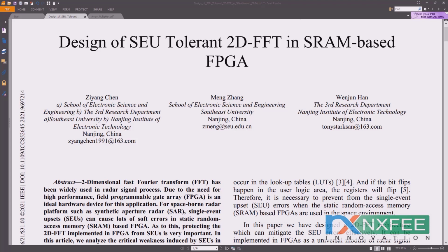This design takes advantage of many anti-SEU techniques. Triple modular redundancy (TMR) is utilized in the FFT butterfly control, and the data buffers are read and written with error correcting codes. Furthermore, the critical storage registers use secure finite state machines, and the findings of fault injections revealed that the reinforcement approaches help to improve the capacity to attenuate SEU impacts.